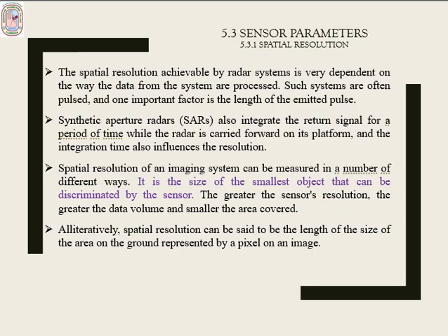The spatial resolution achievable by radar systems is very dependent on the way the data from the systems are processed. Such systems are often pulsed, and one important factor is the length of the emitted pulse. Another example is the synthetic aperture radars. These also integrate the return signal for a period of time while the radar is carried forward on its platform, and the integration time also influences the resolution.